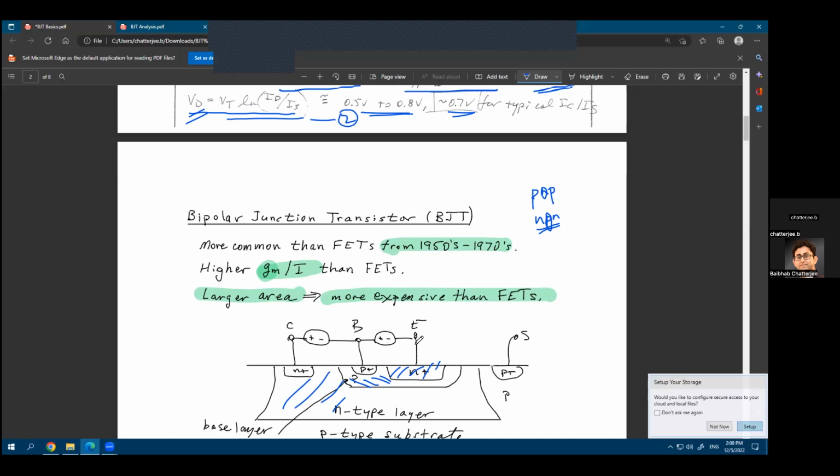So how do the electrons or holes, the carriers, traverse from the source to the drain? It's mostly because of the effect of the field. Because of the field, the carriers have a certain velocity, and because of that inertia, once they have started their travel from the source side, they will reach the drain side anyway.